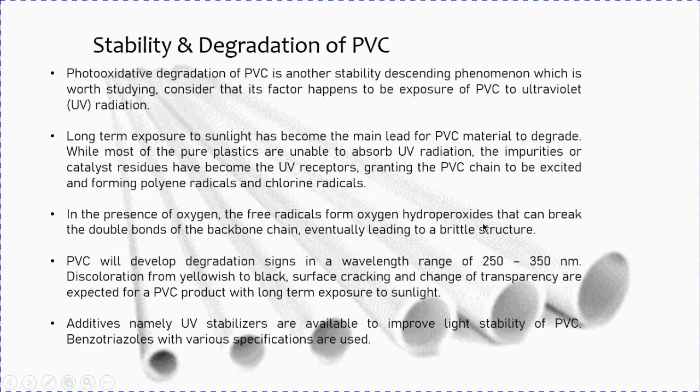In the presence of oxygen, the free radicals form hydroperoxides that can break the double bond of the backbone, eventually leading to a brittle structure. Additives such as triazoles are used to improve stability to UV exposure.